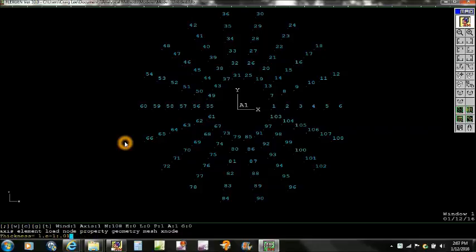The thickness into the page here is going to be 0.01 inches. It could be anything really. This is an infinitely long tube. And we'll take the defaults on the rest. We'll call this just a thick wall tube section. And the elements will all be in a group, and we'll call that thick wall tube group.